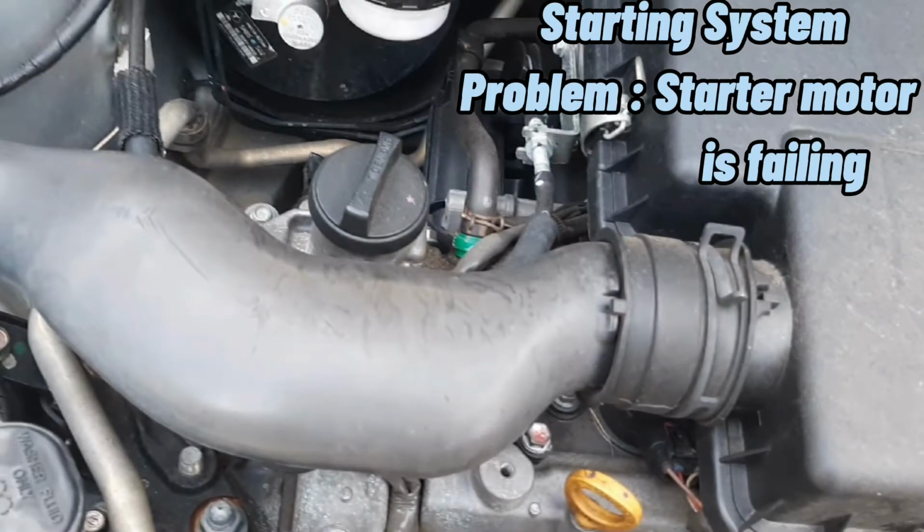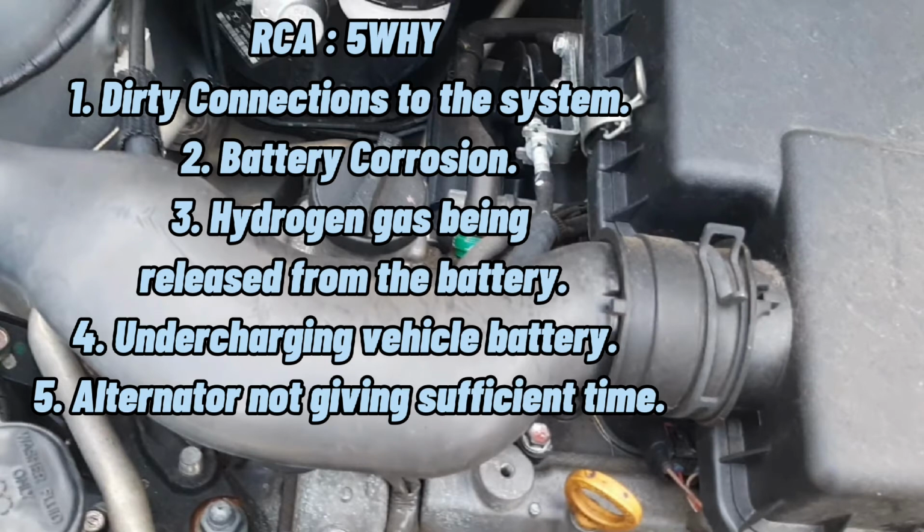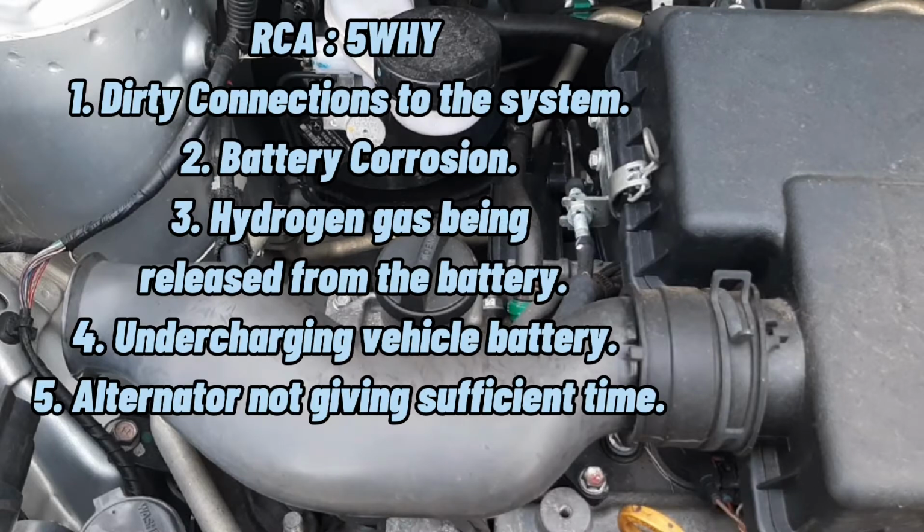As for the starting system, the potential failure is that the starter motor is failing. Based on the RCA of 5Y, the cause of the starter motor failing is because of a dirty connection to the system. And why? Because of the battery corrosion. Why? Because of the exposure to the hydrogen acids from the sulfuric acid inside the battery. And why? Because of undercharging the vehicle battery. Why? The root cause is the alternator is not given sufficient time to replenish the lost battery charge due to the electrical load demand of the vehicle.